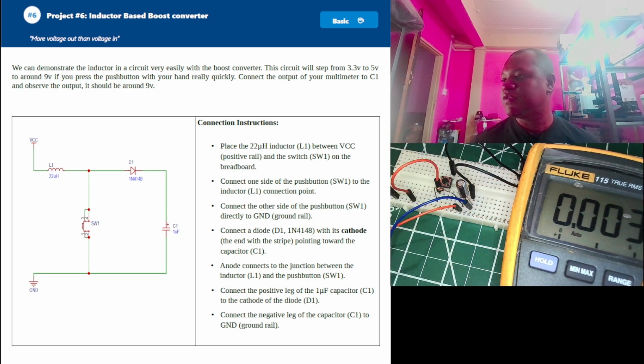And you actually want to use magnet wire, right? There are different gauges of this. For basic experimenting, 22 gauge is a nice fit because it fits into our breadboard really well. 24 I find is a bit too thin. When you start to reach 20 and 18, it's a little too thick for breadboard stuff. But if you have to buy one size, I generally recommend either 22 or 18, right? Even though 18 might not necessarily fit in our breadboard.